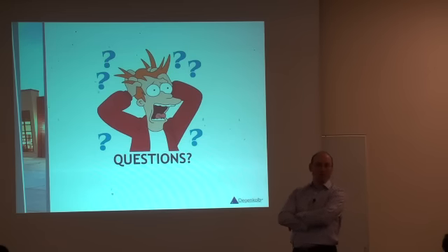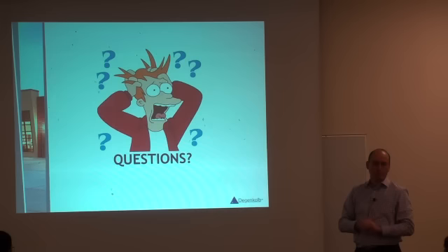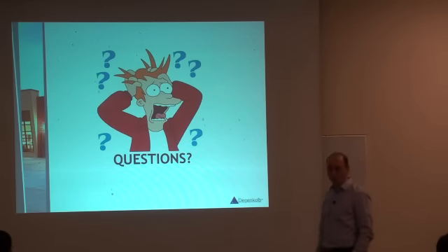When you're reporting 1.23% drift, and you go back and compare two different software and you're getting differences of 40%, it puts things in perspective for you. Now, I would assume that if we get beyond the obvious mistakes and obvious shortcomings of the software and bugs and so on, these results should come much closer together. But that's something that we need to keep in mind.